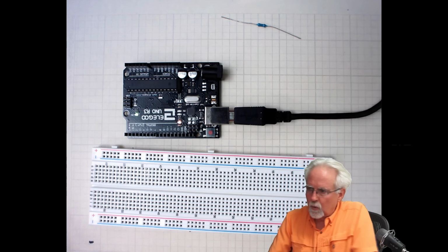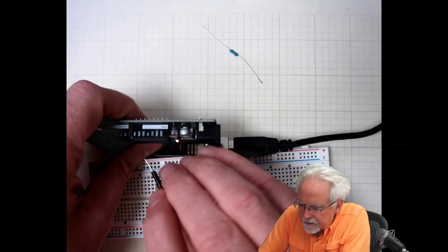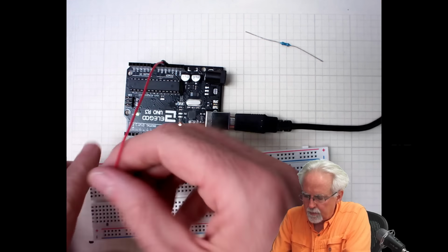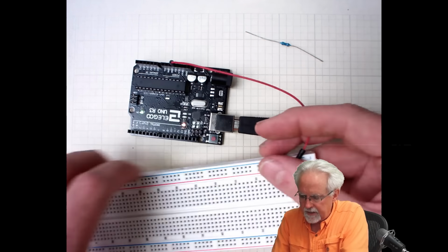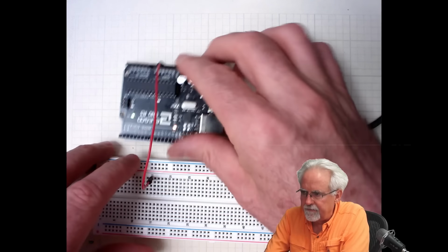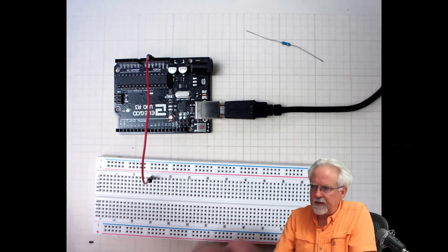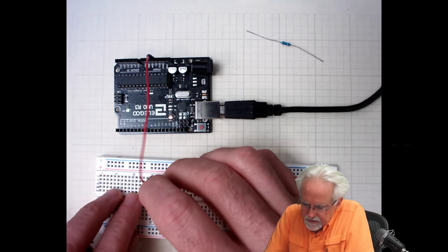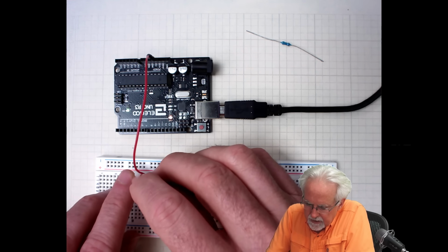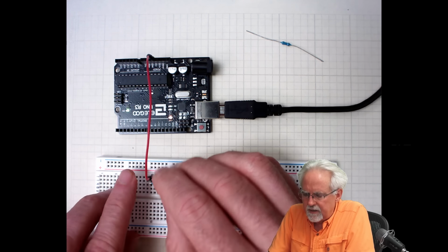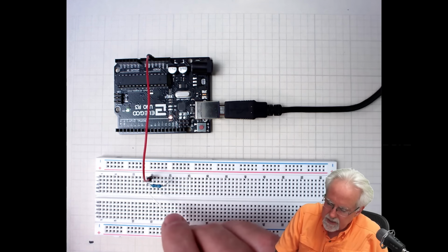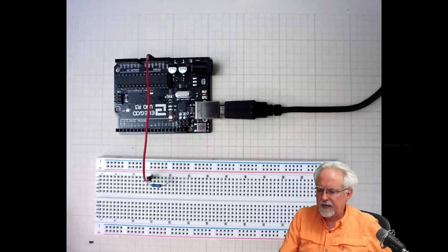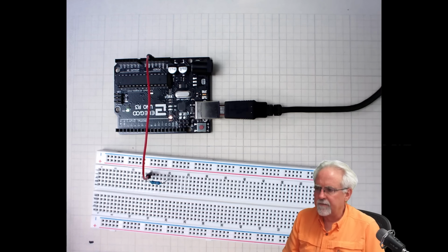I am just going to hook it up to the 5 volts. So I will get a red wire and I will put it into this 5V. You see the pin that says 5V? I will bring it over to, let's say, I kind of like to start in column 15 like that. And then I'm going to get my 330 ohm resistor. One leg is going to go in that column 15. The other leg is going to go in column 20. You understand it doesn't matter specifically what you do. It just matters that the holes in a column are connected. And so now I've got 5 volts to one leg of the resistor.